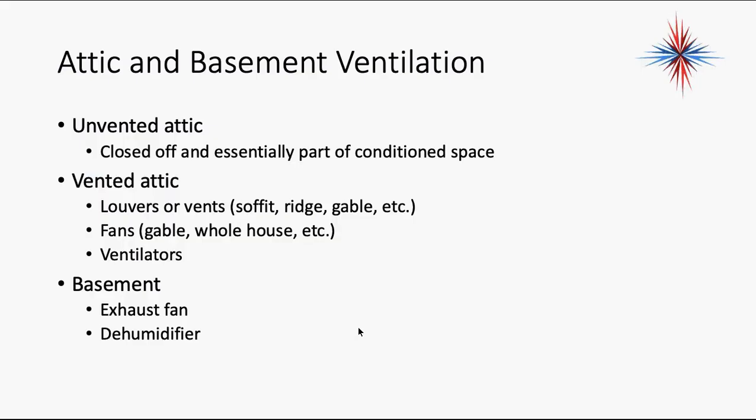And again, I can tell when I open up the front door of a building if they've cut down outside air, because the air is going to pull into the building behind me. If they have enough outside air, when I open that front door to go do a service call, that air is going to push out at me. I can tell without even talking to anyone in the building, just by that, what's going on in the building.